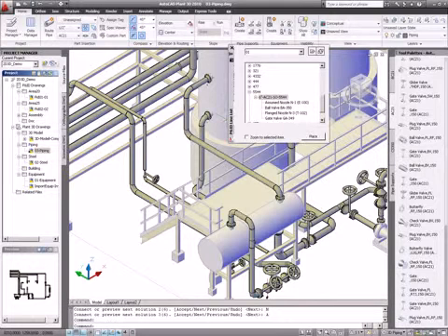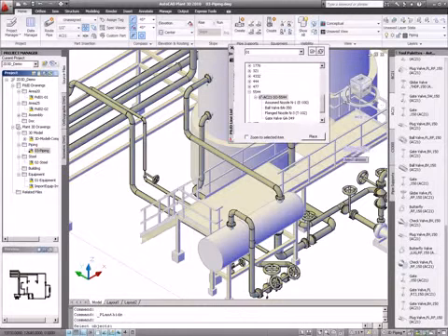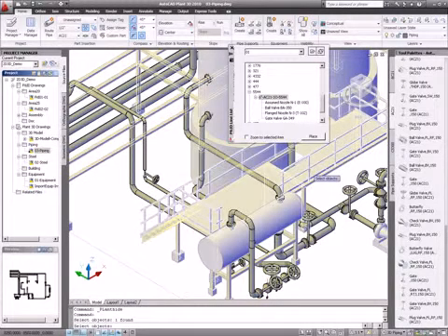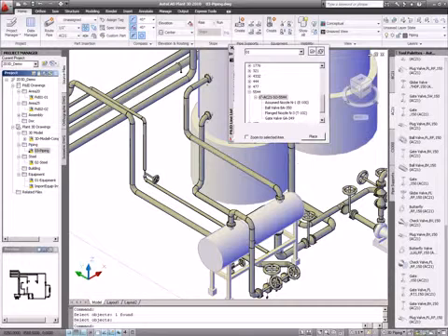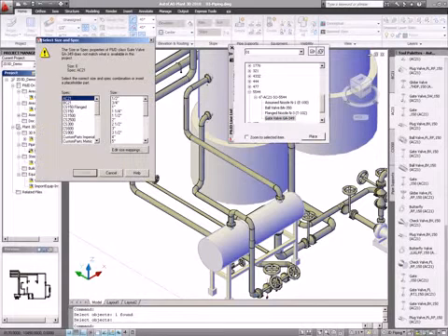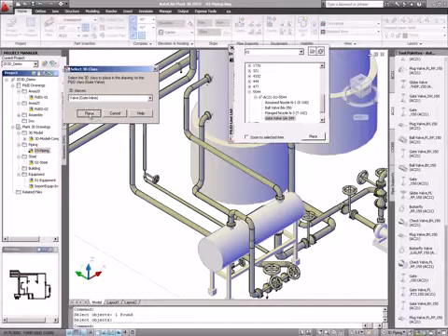The second thing I want to do is add the valves. And remember, we talked about the visibility. In this case, I want to remove the steel section. So I can select hide selected, and then just select the steel, and we hide it. As you see, it's easier to see. So we start with the gate valve, place it, and it's an inline valve.